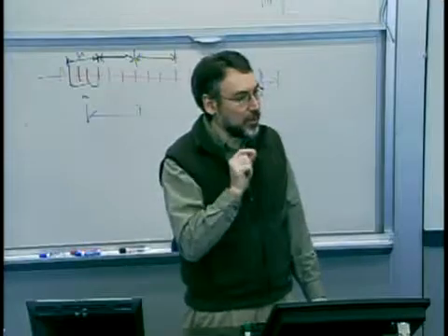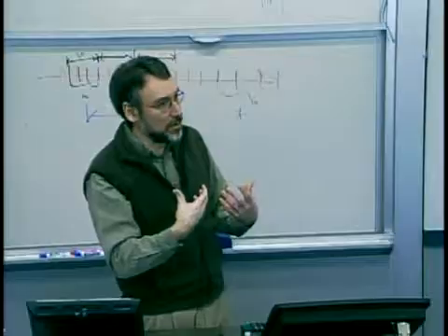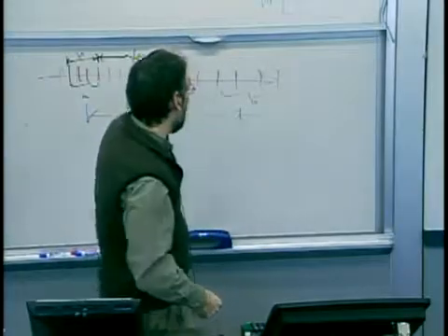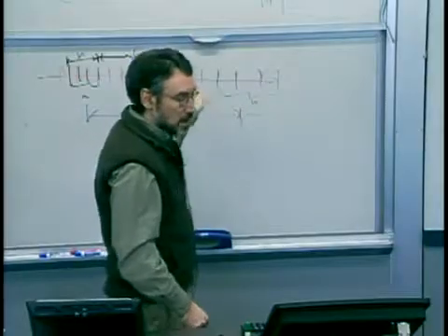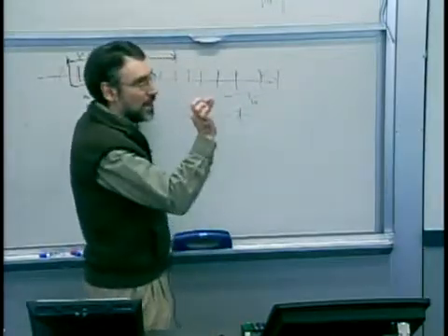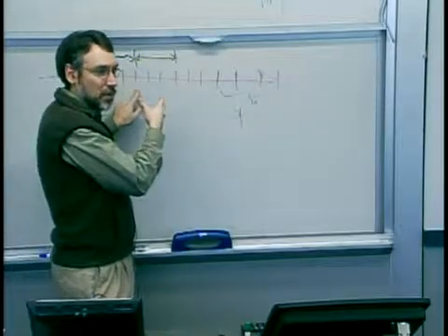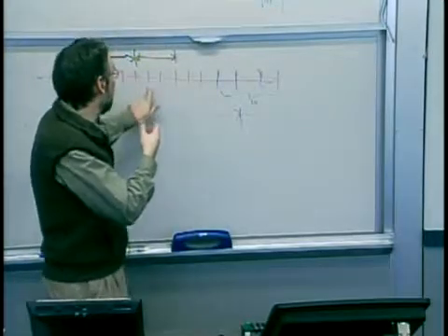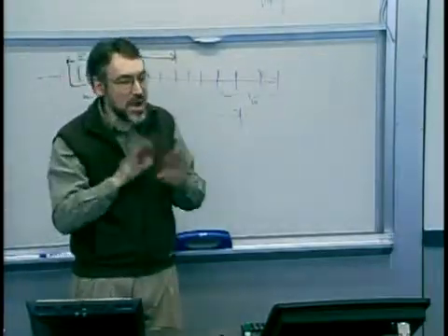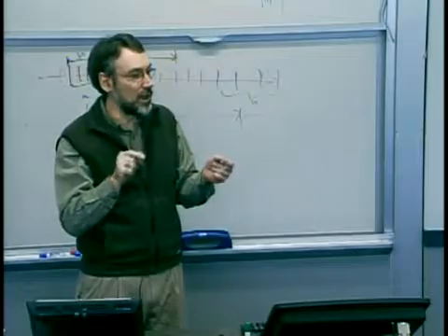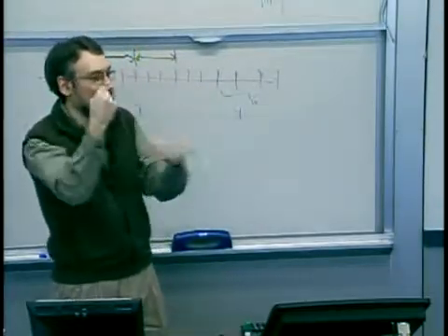If, however, they truly are independent, you can still formulate statistics and probabilities associated with that. In other words, if your process data was independent, from any one point in time, I can calculate the probabilities associated with that. But if I then calculated that for my next point in time using some of the same data, I would never use some of the Western Electric rules, like the probability of 2 points in a row falling above, because they're no longer independent.